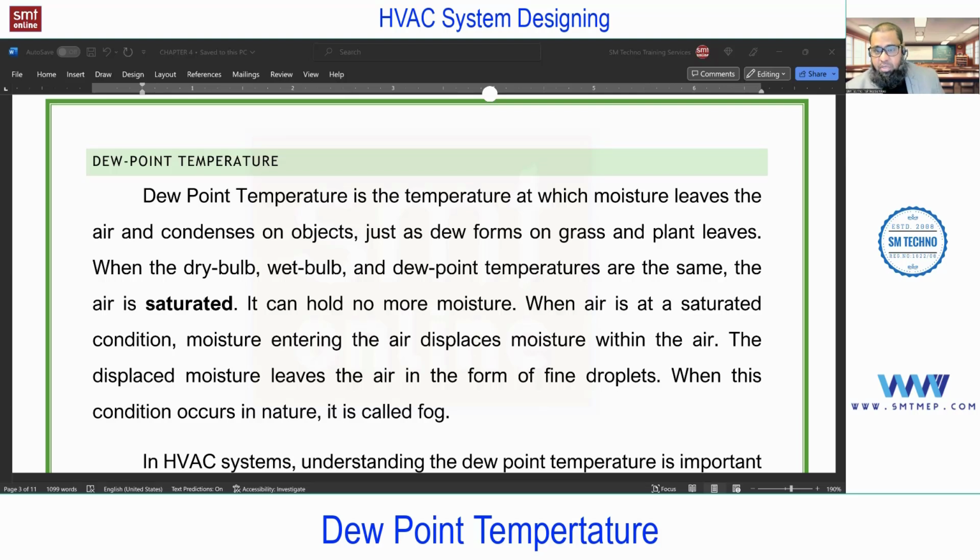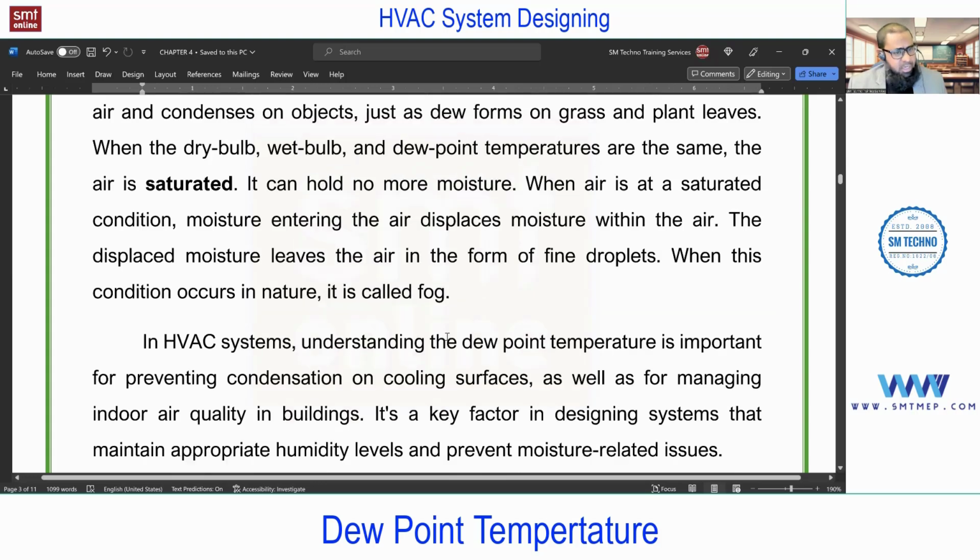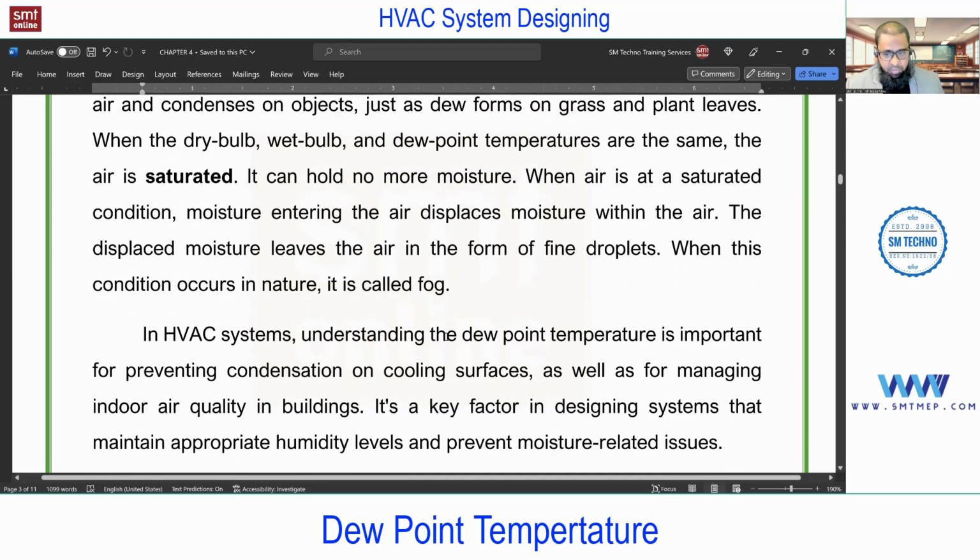And fresh air means continuously providing the outside air, which means with the moisture. Again, that also depends on the outside condition. In some areas you'll find lower humidity, so the process will change. In that case, we require cooling and humidification. But what we are discussing is just general. So I think you got a clear idea about this dew point temperature, which is important.